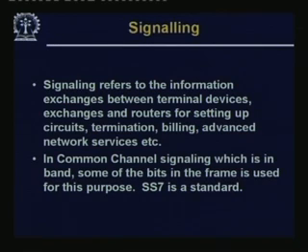And just one other point before I go to signaling, I want to mention that another implication of having fully analog technology in the local loop is that before you can use TDM or other kinds of multiplexing techniques higher up, for connecting between exchanges etc., you need to convert it to a digital signal over there. Okay. So, an exchange usually will have a bunch of codecs.